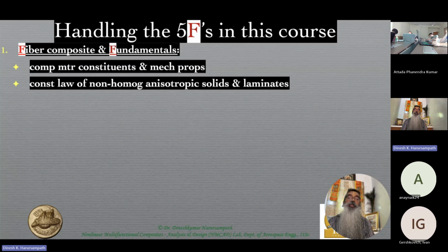Some might be stressed to a large extent in different directions, etc. But all of those are related to each other. And this constitutive law is at a particular point in the structure when you're dealing with what are known as local theories, which is all that we will be restricted to in this particular course. Then we will be looking at something that is not time dependent, not space dependent, but at a given point in a structure, at a given instant of time, if you know the stress, you should know the strain. Okay, what is the relationship between them? That is essentially your constitutive law.